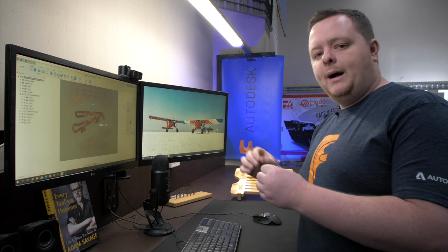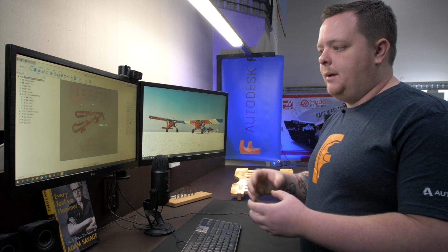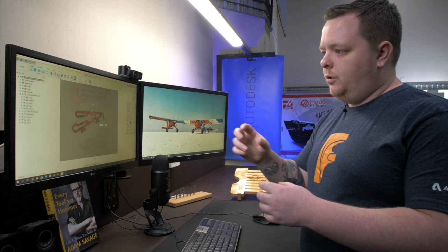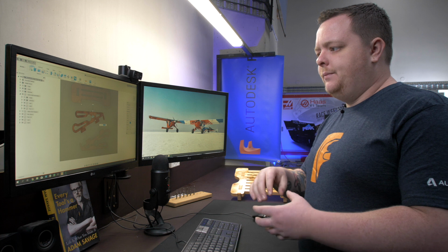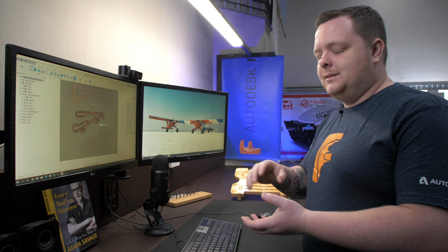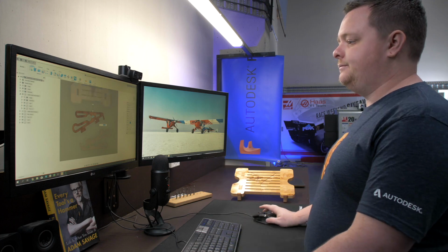Especially in wood, if you leave too small margins between parts, one thing that'll happen is tear out, where those little margins will actually tear out. And if you've left tabs to try and hold the part in, the parts are more likely to fly out or come out because those little margins have ripped out. I've seen it many times where people leave these tiny little margins and put tabs on there, and unfortunately it's just not strong enough. So it's just something we do need to bear in mind when we're doing this.